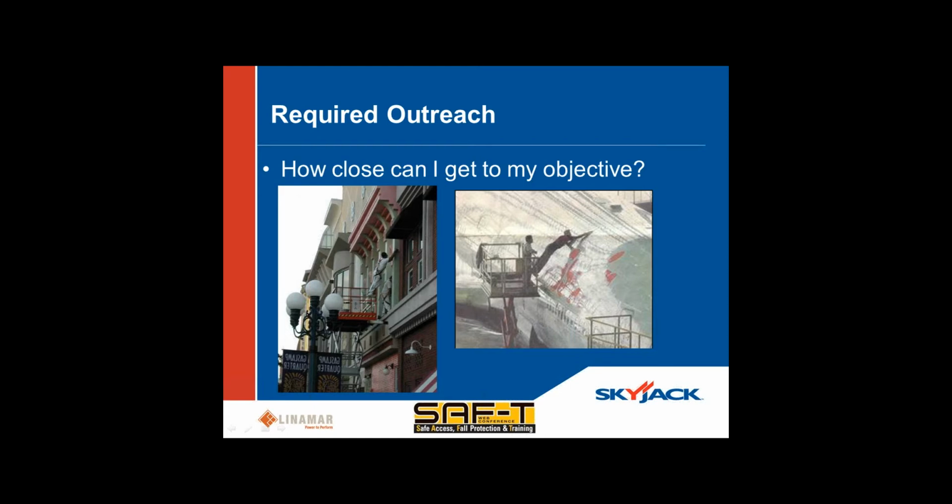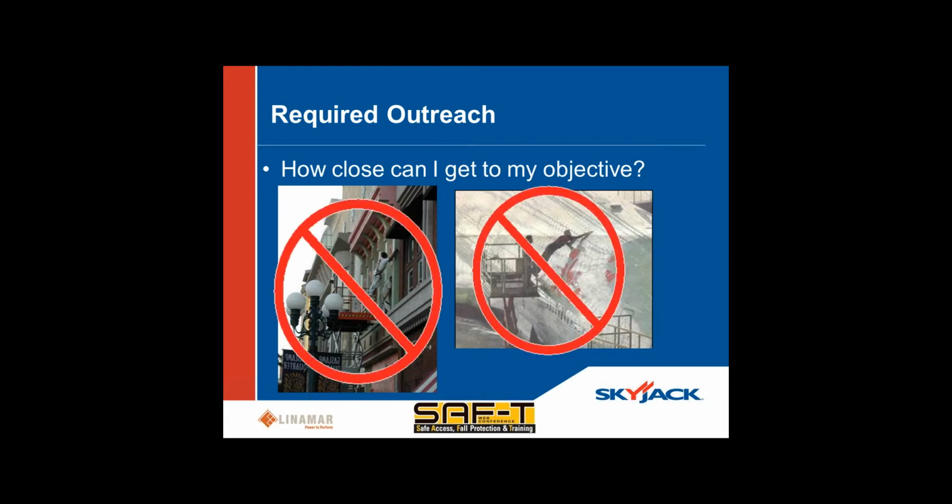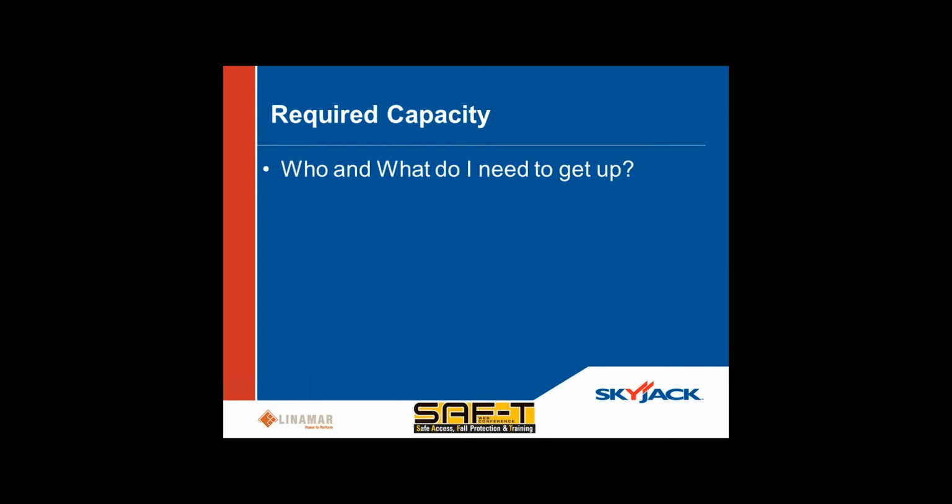And obviously on the right-hand side there, that's certainly some inappropriate behavior and obviously the wrong lift for that particular application. You really do need some other type of lift that will allow you to get up and over the contours of that aircraft, or you may need a specialty type of lift that allows you to get there as well. And so in both of those cases, in keeping with making sure everybody knows that that's inappropriate practice, we've put the do not do this symbol on top of it.